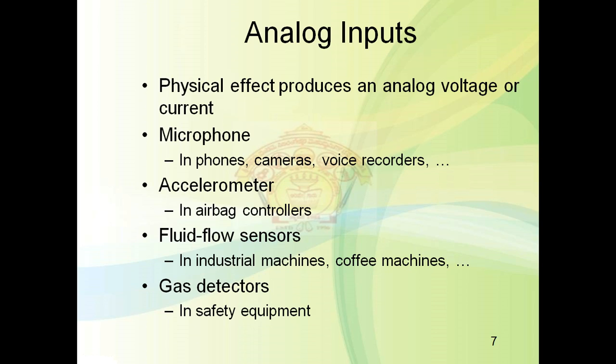Another example of input devices is the fluid flow sensor. There are numerous forms of sensors that rely on different effects to sense the flow. One form uses temperature dependent resistance. Two matched resistors are self heated using an electric current.